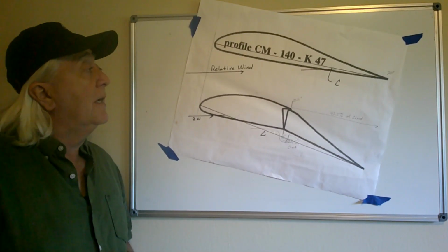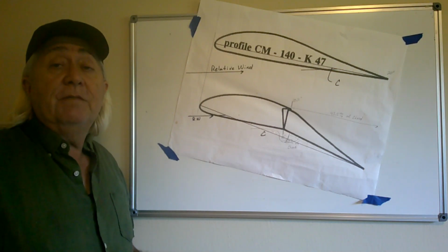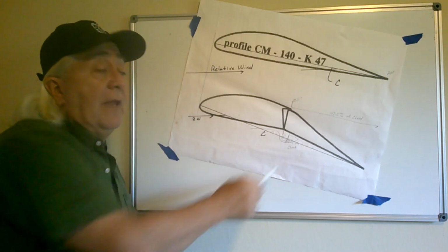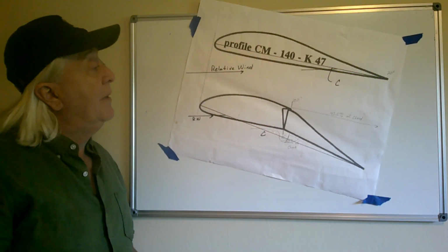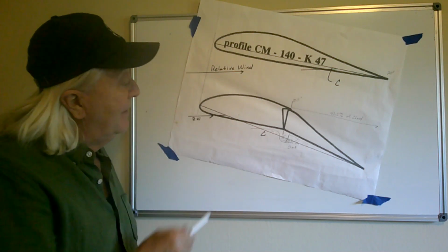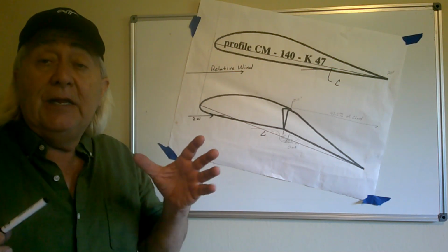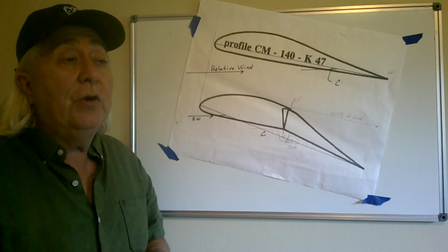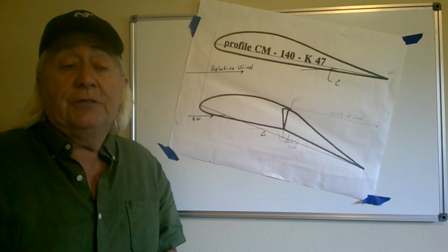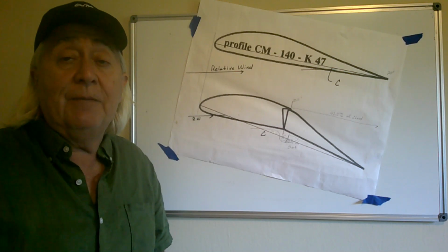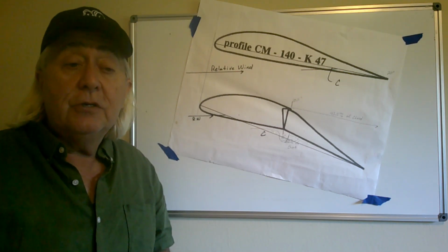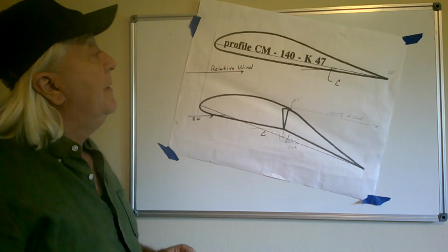So here I've set up a print of the Flair airfoil, both in its base configuration with the flap deployed, and I've taped it up here on my whiteboard because I didn't want to have to try to redraw it all. And I put in some relative wind. And I hope that this explanation is more intuitively obvious than what I showed you in the actual aerodynamic data, the computational fluid dynamics, to show you how a stall can occur just by deploying the flap.